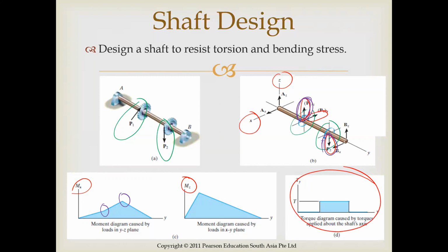What I didn't show you on this slide is the shear diagram. Typically, it'd be easier to start with your shear diagram, and then you can go quickly from your shear to your moment diagram. And then in the other direction, we have just this one horizontal load that's occurring here, where we have this change in the slope of our moment. So you have two different moment diagrams depending on which direction the moment is about.